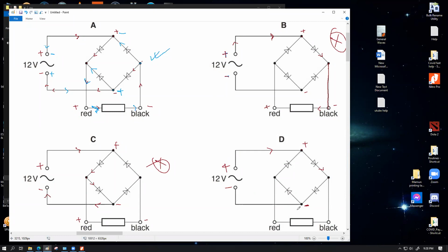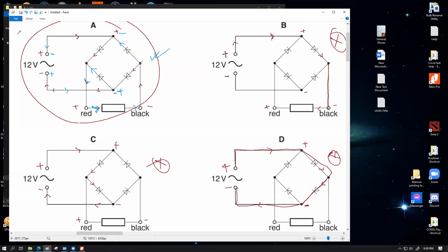Obviously through the diode. Beautiful. So all the current will flow through the zero resistance path and complete the circuit, reach up to the negative end. No current will flow through the resistor whatsoever. So that's an error because once again, this entire pathway has now become a short circuit path. So this is also not acceptable. So ultimately, you only have this choice available. This is the correct response.